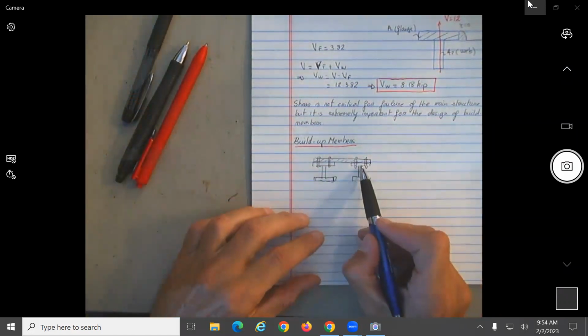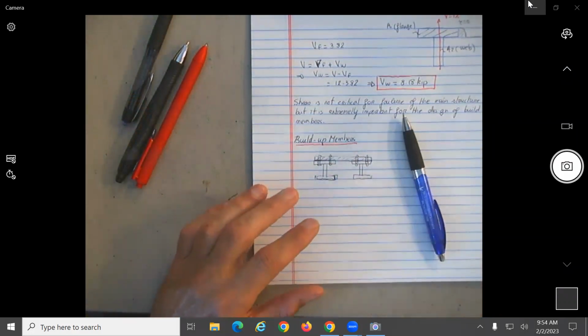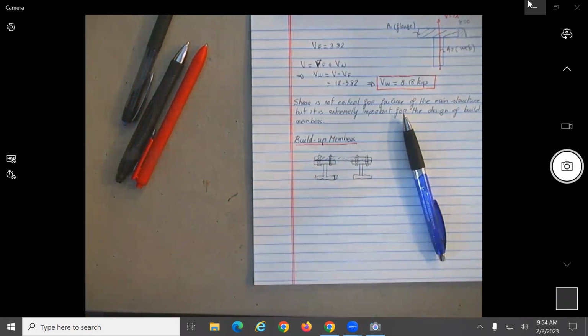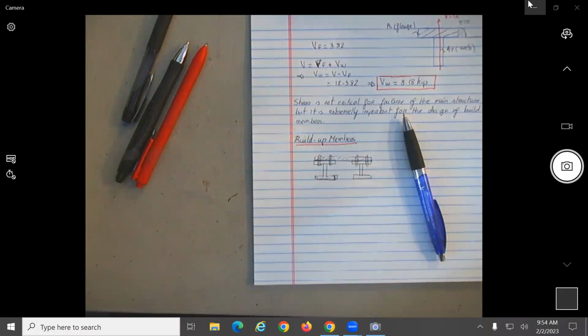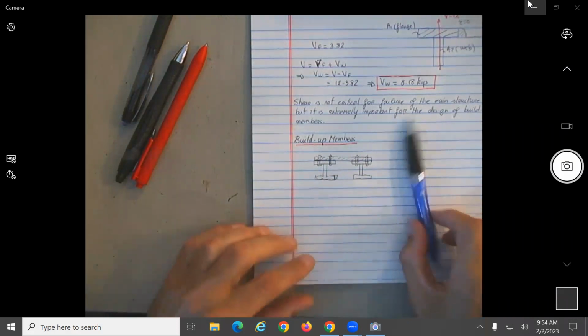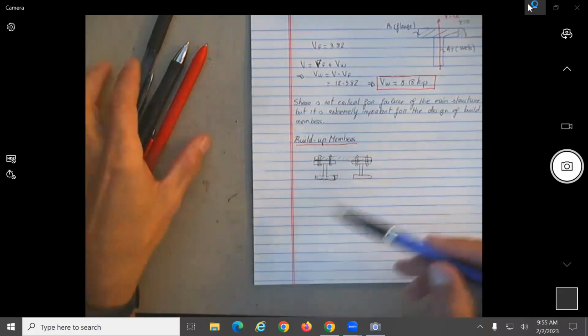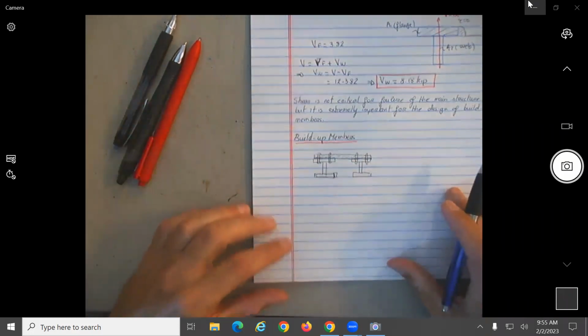Because when it's bending, what's going to happen? This structure is going to deform, this shape, and the top one, the same thing, no? Yeah. So between them, what will be the load? It will be shear, no? So the bolts over here will bring you to what? Shear, no? So that's when it's really important, what is the shear over there? So we can do the design of the bolts and so on.